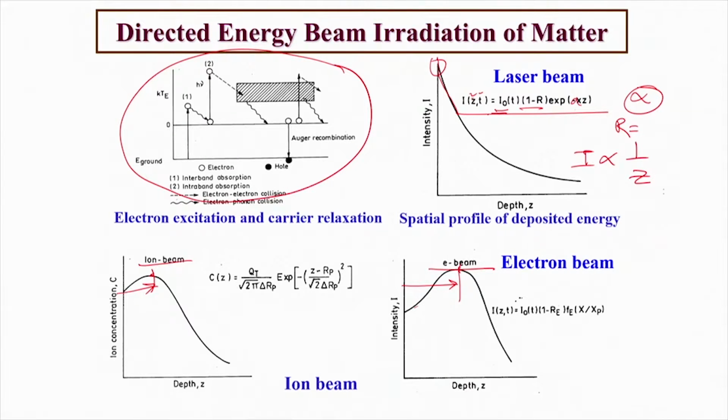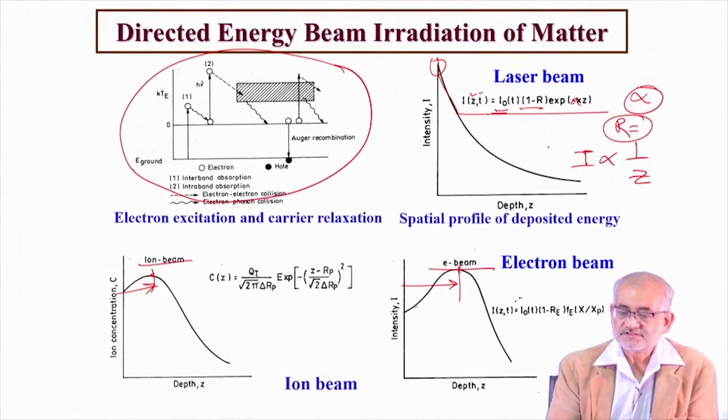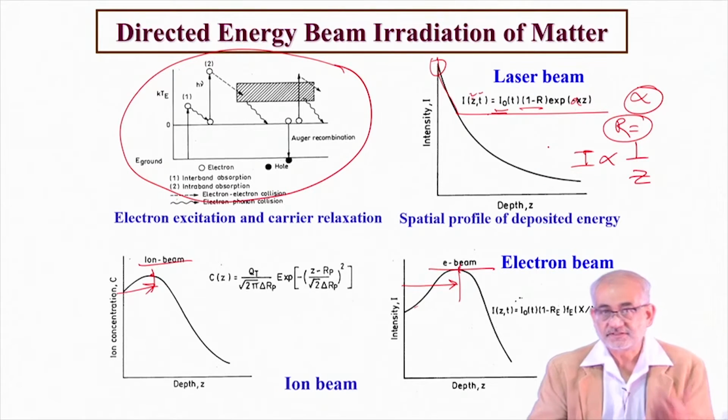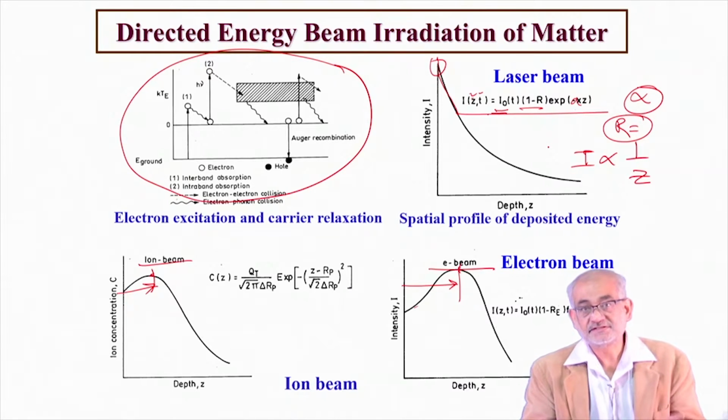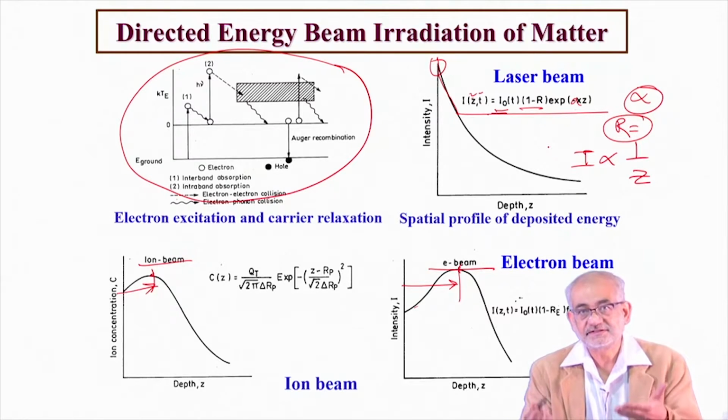So one would like to play with reflectivity. One can use certain films or coatings or make the surface rougher so that the coupling efficiency increases. So reflectivity is simply: if there are 100 radiations incident at a given point of time in a given area, how much of it is actually able to interact and couple, and how much of it is actually getting reflected back.